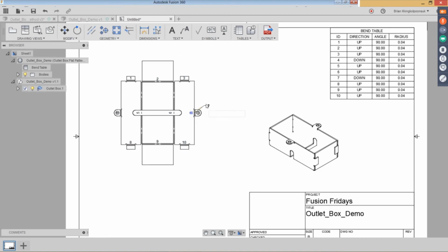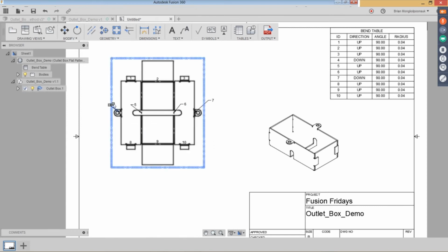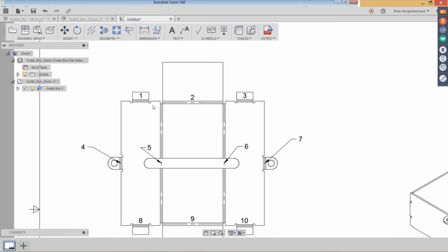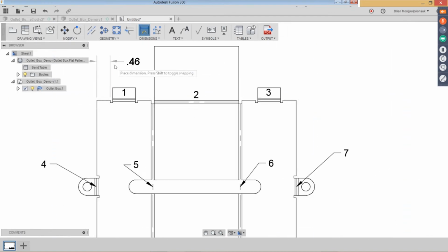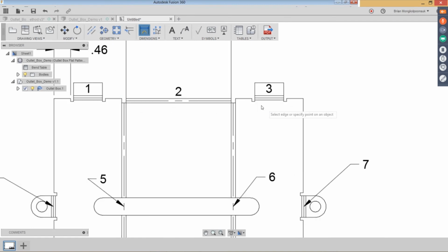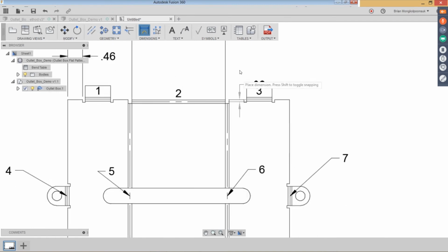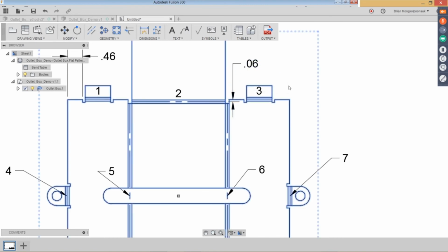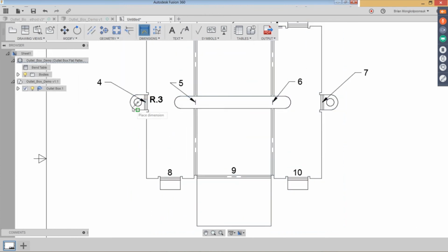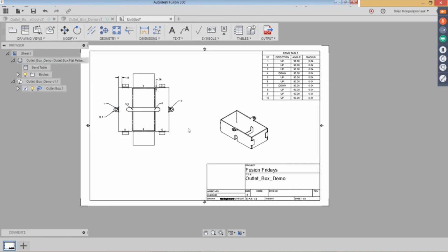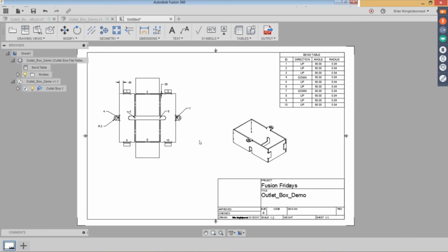And then for good practice, it's good to make these all facing the same way and easily visible for the reader to view. You can also dimension the part, which is very important in the drawing. So then the person bending this will know how far or where exactly they can create that bend. I won't go into dimensioning each one, but that's the general idea.